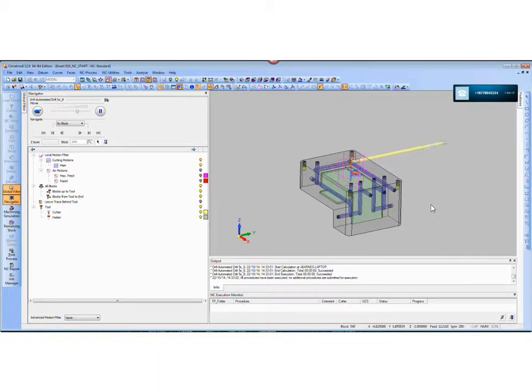And that's another thing I didn't mention was cost. Yes, these drills are expensive. They're a lot more expensive than a high-speed steel drill, but you have to consider the cost of the hole, not the cost of the drill. How long does it take to drill these holes, and amortize the cost of that drill across all the holes? Don't get sticker shock and say, "Well, that drill's too expensive. We're going to order the cheap high-speed steel ones." I understand that there's always limitations with resources, but please consider the cost of the hole, not the cost of the drill.